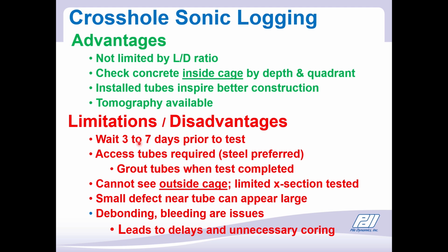Limitations and disadvantages, well, we have to wait for the concrete to cure before we can do the testing. And the typical time is somewhere between 3 and 7 days. And if we see a problem, then we might have to retest after a few more days. So there can be a considerable delay in time to the construction process to verify that the quality is good. Of course, we want to verify the quality is good because once we've built a structure on top, if the foundation has a problem and fails, then we're going to have to tear the whole thing down. So it is important to verify the quality of the foundation.